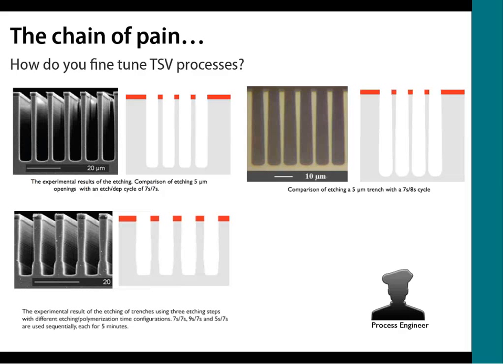And as I said before, all of these tools might be good ways to help out researchers that are developing the process for their device and figuring out how to manufacture the device. Or they could be used to teach students about the intricacies of, say, silicon wet etching or dry etching, and how changes in process parameters will affect the etch.